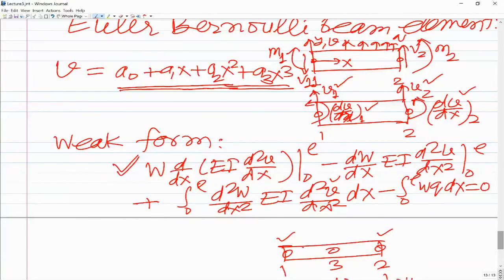In the previous case, the two-noded truss element, both differentiability and inter-element compatibility lead to a minimum of a linear polynomial. In this case, compatibility leads to a cubic polynomial, but the differentiability requirement within the element leads to a quadratic. So we take the highest, a cubic polynomial. Whether the variable and derivatives of the variable should be degrees of freedom depends on the order of the differential equation, what the primary variables are, and the continuity of those across the element.